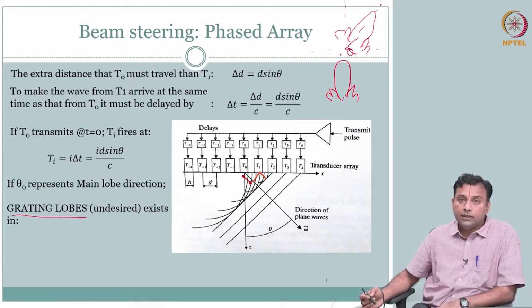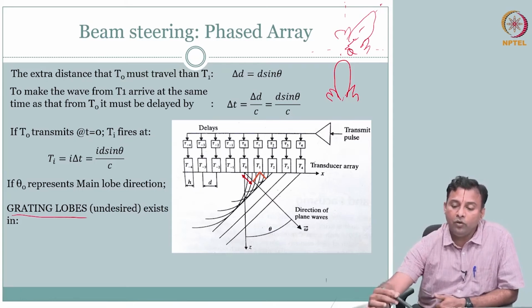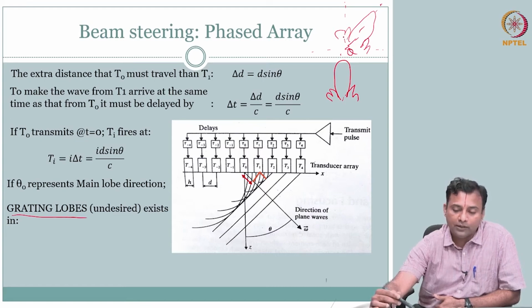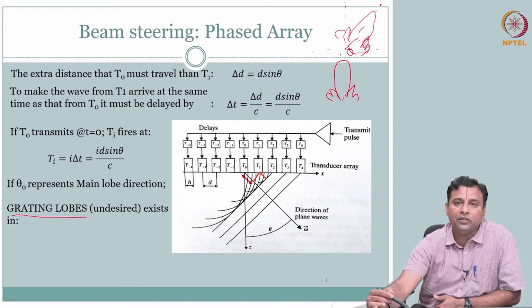So the problem is, when you are trying to look at this direction theta and you are sending the signal in theta direction, whatever you receive, you are going to think that it is coming only from theta direction. Of course, there are these small side lobes, but we integrate over the side lobe, so it is just reducing the signal quality, but it's okay. It is a problem, but side lobe we know how to do apodization to minimize its effect.